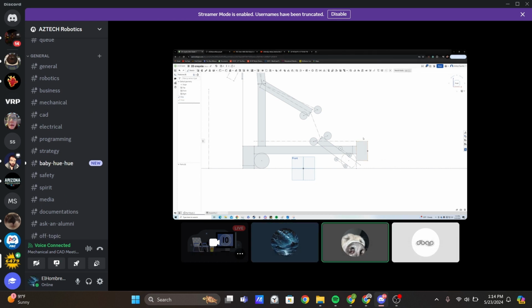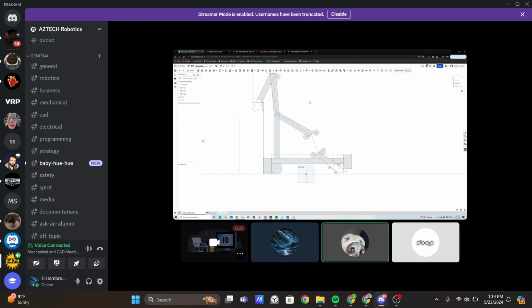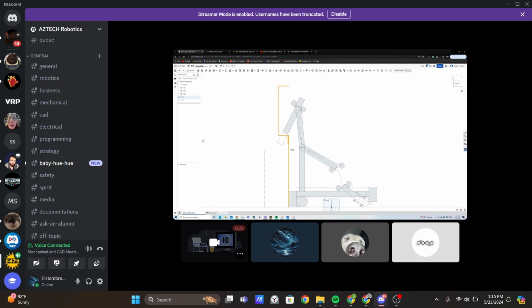One is very clearly higher off the ground than the other, and that's just because we decided to do an under-the-bumper intake. So this is 2 inches off the ground. I think the highest that your bumpers can go is actually 7.5 and not 7. So this line is at 7. You might want to raise this bumper height a little bit, but it's not super integral to the rest of the design. After I had my drivetrain in, I put the amp in. So that's these lines in here.